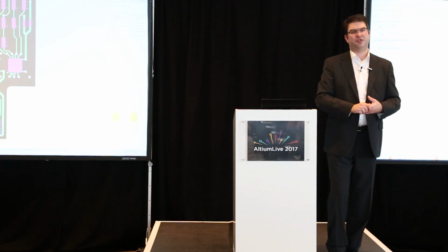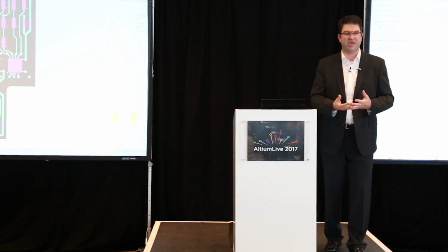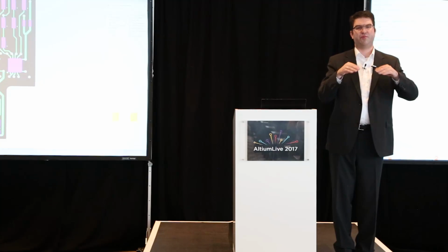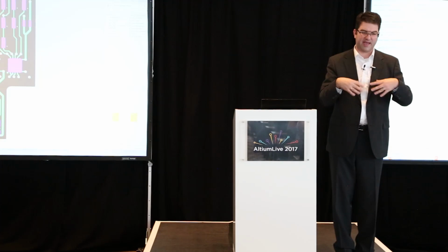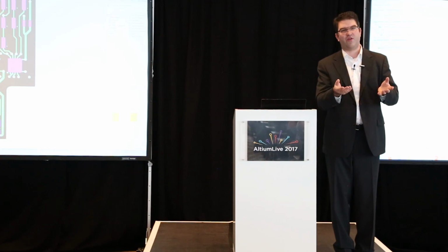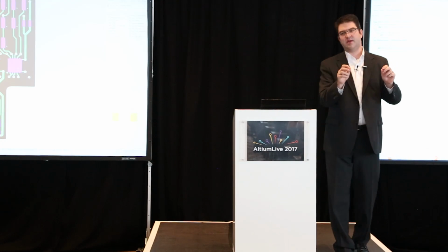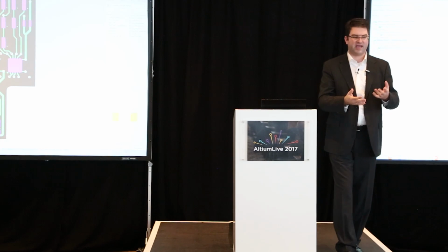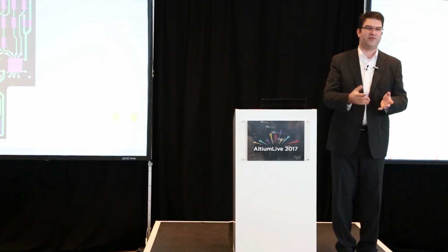You definitely need to know what you're doing. So we have huge experience. We know from each prepreg which we use, what's the amount of typical free resin which can flow. So a prepreg, I just go on a little bit wider. A prepreg, most of you hopefully know, is like a glass cloth pre-impregnated with resin. So it's hardened already a little bit so that it's not tacky anymore. So you cannot use every part of this prepreg. So we know like at 1080 how many % of the resin will flow out there.